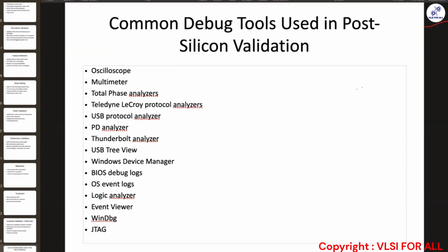And then you try to give certain commands, and check what that register value is, how it is behaving. Okay, from sleep, if it is coming back, then this particular register is giving this particular value, which is again wrong. You cross check all of these details with certain documents, basically internal documents. You will have specifications, data sheets, and other internal documents, whichever you would need, you refer to all of that and then confirm whether it is behaving as it should be or not.